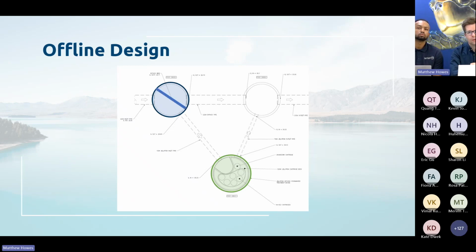And then there is a weir that sits in the receiving manhole that diverts the flow first to the treatment device, and that weir is set at the driving head level of the treatment device downstream. So once the water reaches the driving head level, we know that the device is operating at the design treatment flow rate, and all additional flows can go straight over that weir and bypass.